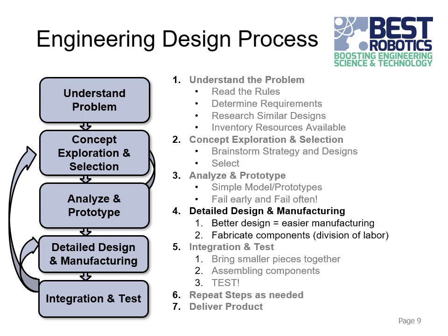So then in the detailed design and manufacturing phase, this is where you're actually building parts of the robot. At this point, you should have a pretty good idea of the overall system design, and so you should have an idea of how you can divide things up. A lot of times this is divided into a drive base and an arm or end effector or grabber, and then the software is another important component. And by dividing it up, everybody can work on their parts at the same time, in parallel, and actually start building things.